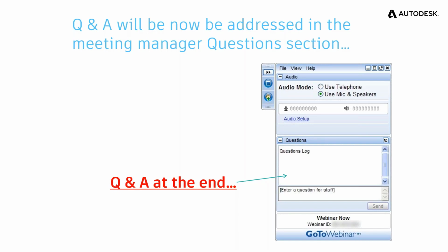If you insert a dynamic block into an existing drawing with the block of the same name, will the existing blocks move? I think what he's asking there is, as long as there's not attributes, you would have to do an ATTSYNC on it if there's attributes. But other than that, if something in the block is moved, it's going to go to its default state for anything in an existing drawing.